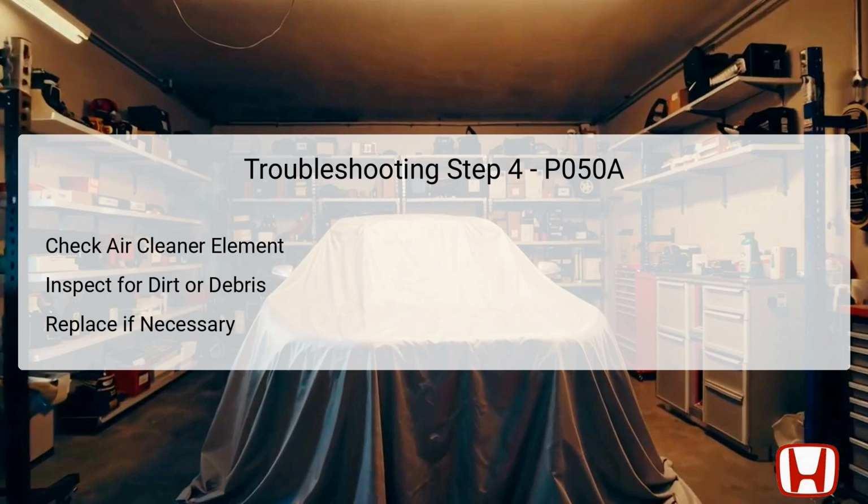A dirty element hampers airflow and can trigger the DTC P050A. If the element is found to be dirty, it needs to be replaced to restore proper airflow. It's essential to use a compatible air cleaner element that meets Honda specifications. If the air cleaner element is okay, proceed to the next troubleshooting step.